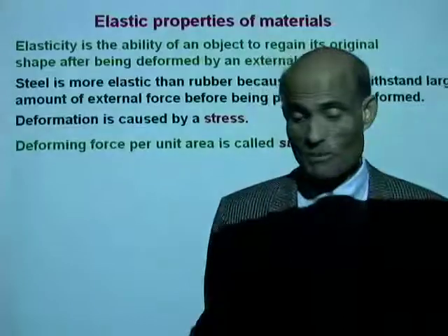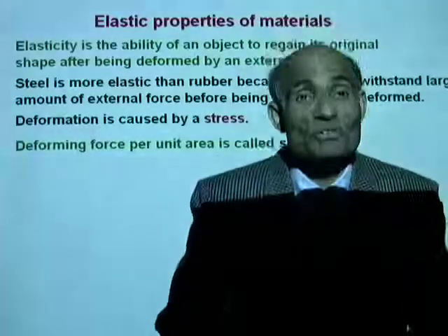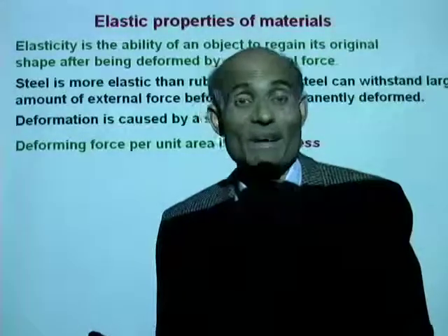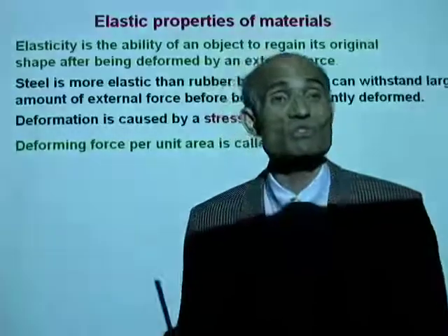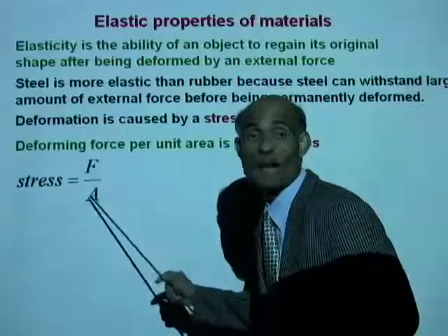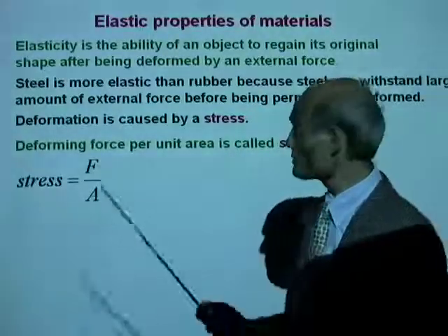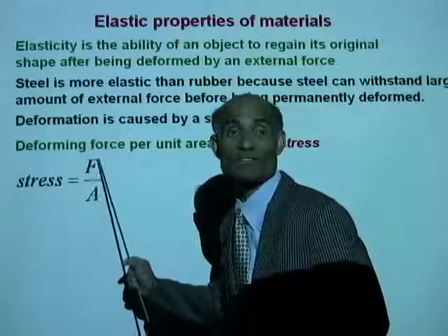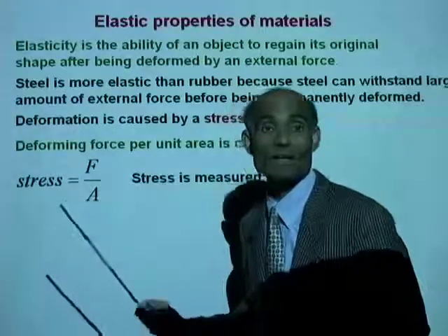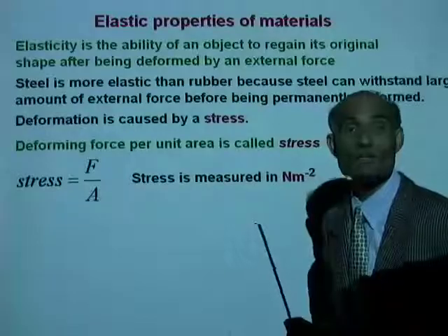If I can apply a certain amount of force on a certain surface, what is the force per unit area? And that is a measure of stress. So stress can be defined as force divided by area. Force per unit area. What is the unit for measuring stress? Force is measured in Newton, area in meter squared. Therefore, stress is measured in Newton per square meter.